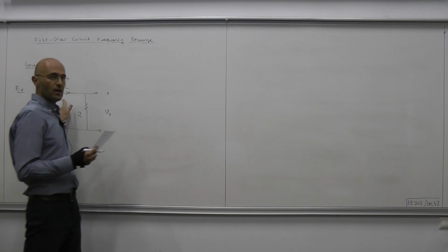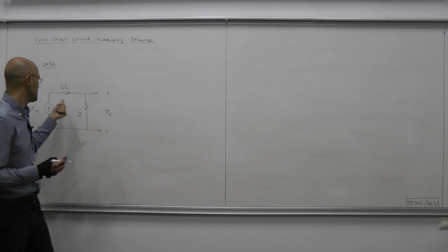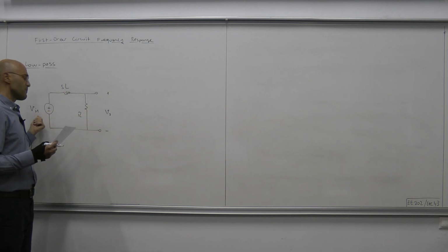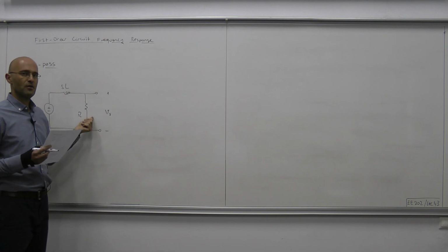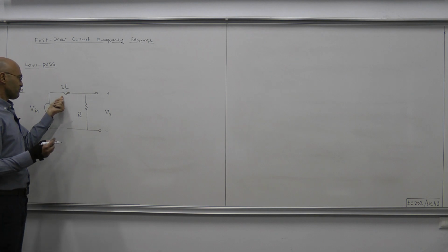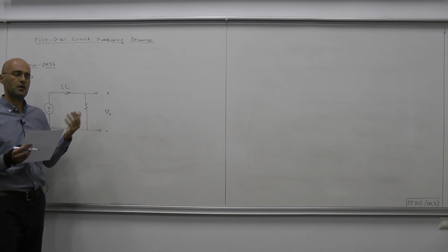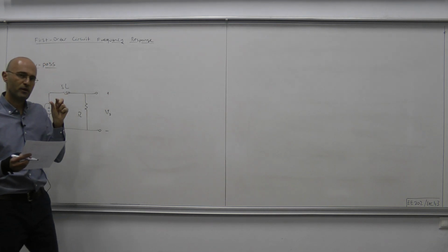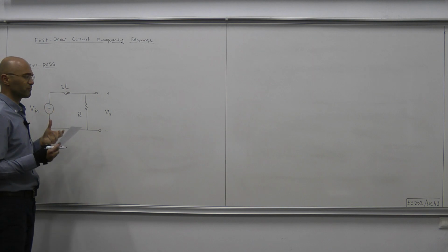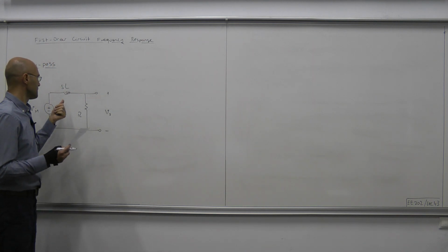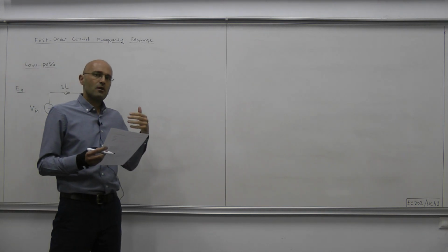Here we have an inductor. We know that at DC steady state, the inductor behaves like a short circuit. So when this is a short circuit, all the input voltage will appear at the terminals of the output resistor. The impedance of the inductor is J omega L. So as you increase the frequency omega from very small frequencies close to DC steady state, where we can take omega equals 0, to larger and larger frequencies, the magnitude of the impedance J omega L becomes larger and larger.